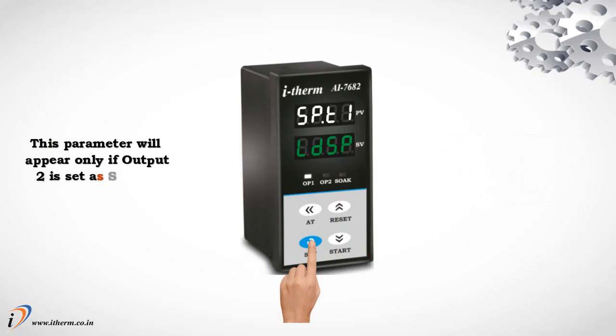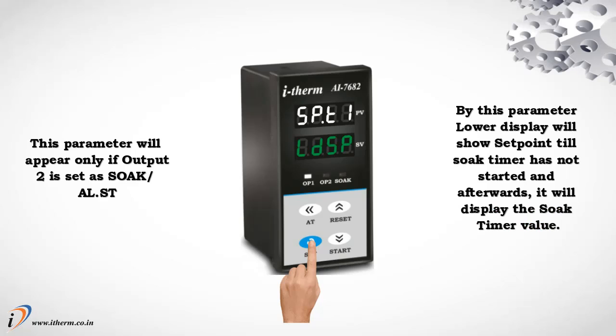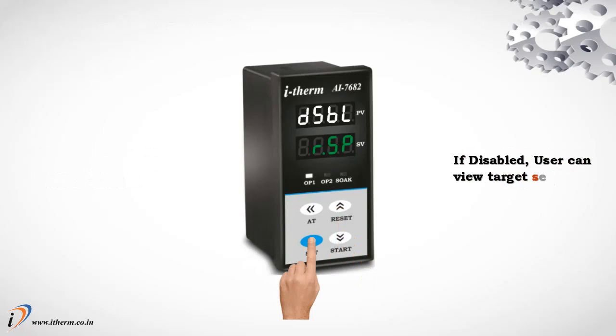This parameter will appear only if output 2 is set as soak, alarm soak time. By this parameter, the lower display will show the set point till the soak timer has started, and afterwards, it will display the soak timer value. Parameter 30, lower display ramping set point. This parameter will appear only if ramp rate is enabled. If enabled, user can view ramping set point. If disabled, user can view target set point.